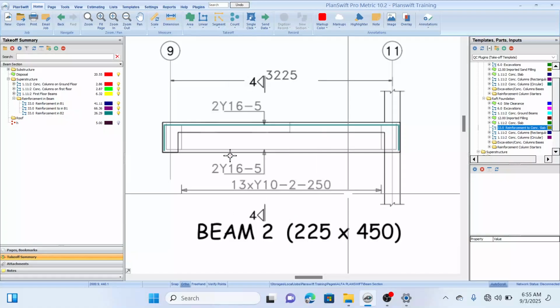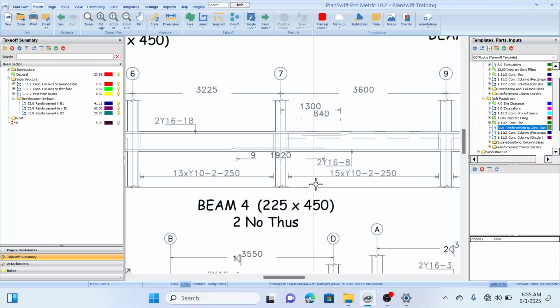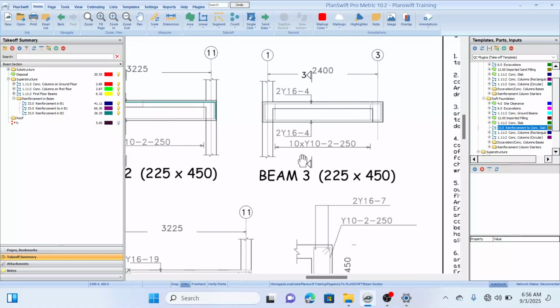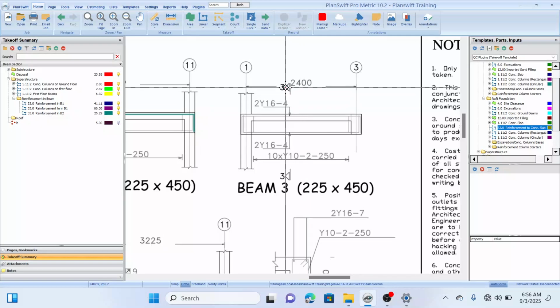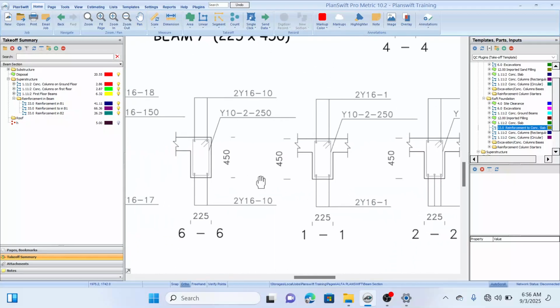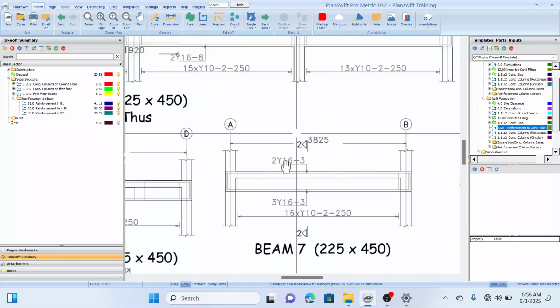Let's measure that of beam 3 and beam 4. So we'll stop at beam 4. I think with that, you guys will be able to measure the remaining reinforcement. Okay, this is our beam 3. And the section through beam 3 is section 3. Let's check the detail in section 3. Where's section 3? Okay, this is section 3. Yes. What we have in beam 3 is the same as what we have in beam 2. We have 4 reinforcements here, 2 bottom bars and 2 top bars.